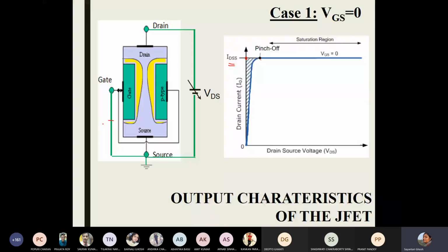Okay. So I want to apply some control voltage, some reverse bias voltage between gate to source now as a control parameter. I want to make VGS something other than 0. If I want to apply more and more negative reverse bias through the junction, then I have to add a battery like this. As soon as I add a battery like this, the entire picture remains the same.